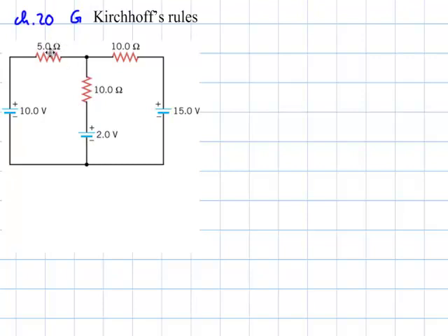They want us to figure out what the voltage is on this one. So that would be a variable, an unknown. Notice that we don't know what the voltage is on this one or this one, but we don't have to figure them out. However, these are unknowns as well. So 1, 2, 3. We have 3 unknowns. We have 5 equations, which means we have an overkill if we write them all down. Therefore, among those 5, we choose 3 to match the number of variables, and those are the ones that we write down. Among the 3 loops, it makes sense only to write 2 down.